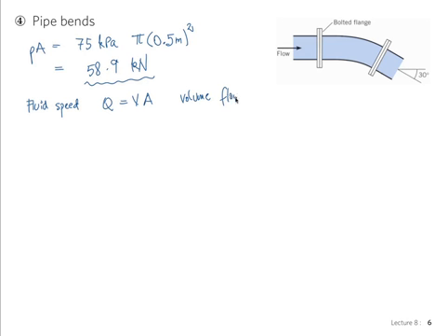This is what's given. And it was 2 cubic meters per second. That's the information that was given, volume flow rate. So we need to get V as Q divided by A, or 2 cubic meters per second divided by the area, which is pi times 0.5 meters squared. And as it should, I obtain meters per second in my units.